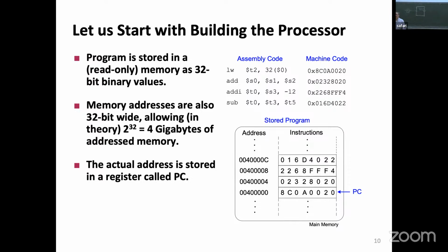Is that okay? Clock comes. Program counter says, go here. We fetch some data. Now, this data is a larger 32-bit value. It comes out, and what we are now going to do is we are trying to figure out, reading the one instruction, is this what we did? Program counter tells us where to go. We go here, and we read out from the memory. This takes some time. It doesn't happen instantaneously. So we read out from here. We have a 32-bit value. And this value, we know that we should interpret this as an instruction.